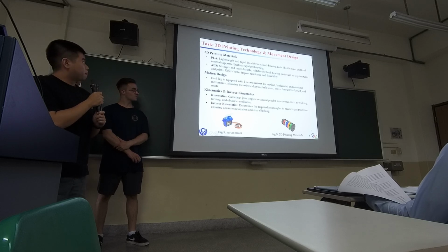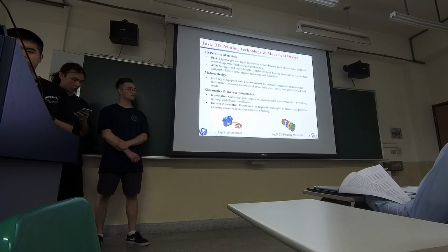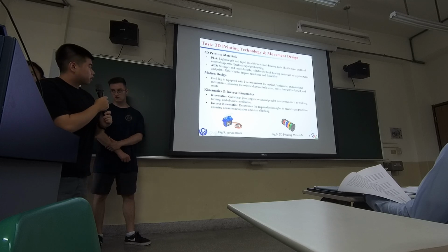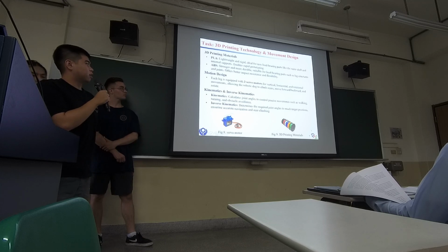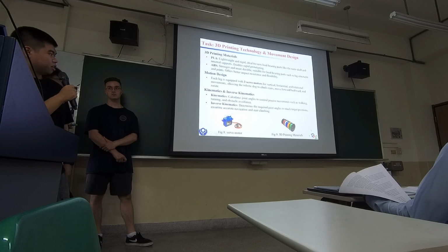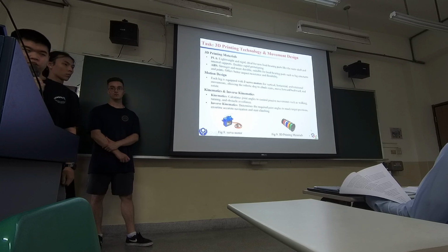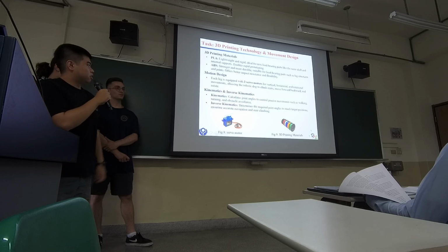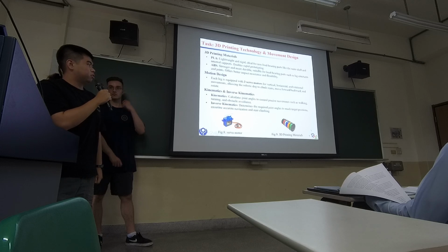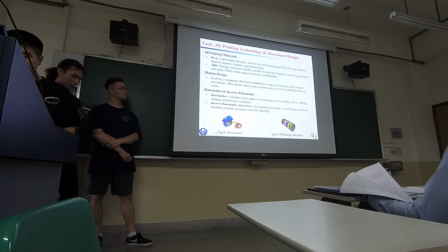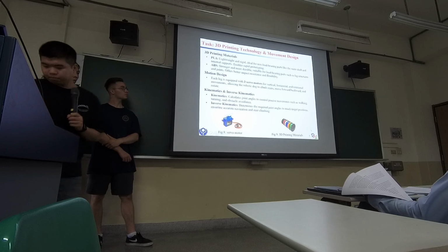And for kinematics and inverse kinematics, we calculate joint angles to control precise movements such as walking, turning, and obstacle avoidance. And in inverse kinematics, we use it to determine the required joint angles to reach target positions, ensuring rough terrain navigation and stair climbing.